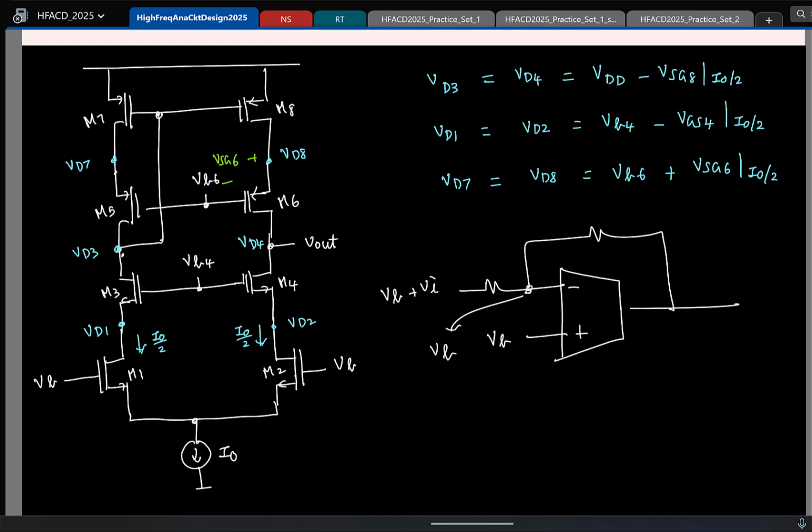No, what is VICM then? Common mode is essentially the average of two quantities. Common mode is a fancy definition of the same. So what is the average of the two inputs? So here there is no small signal component. In this configuration, no, but let us say I put it in something like this, a unity feedback like this. So now what will be this voltage?